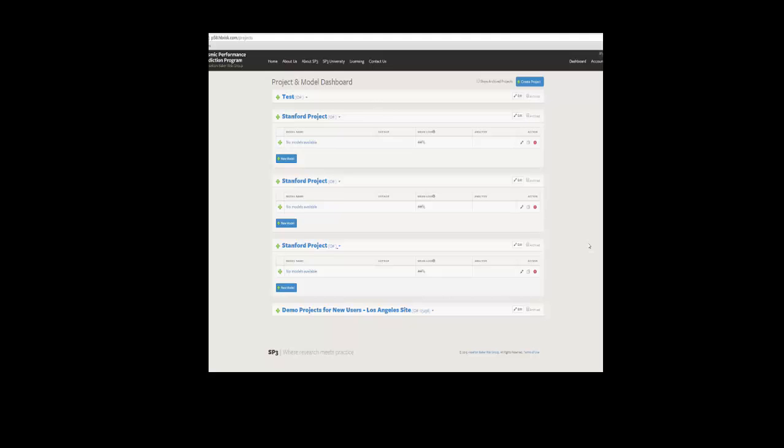Jack, Baker and I decided to do it because there wasn't a way to do it, and we felt P58 would be something useful for the profession. The alternative right now is PACT, but PACT doesn't do the REDi analysis. So the only alternative in existence is that ARUP has some in-house software that they run REDi with. But no, there's no other publicly available alternative, which is why we made it.